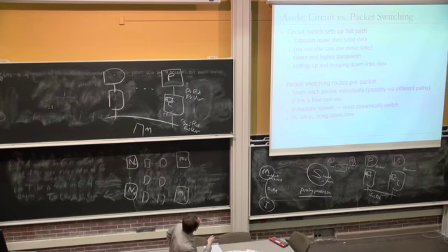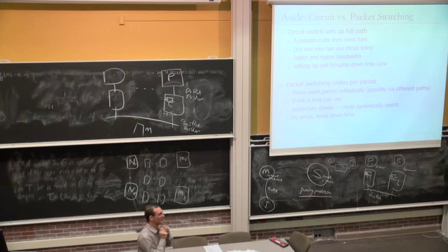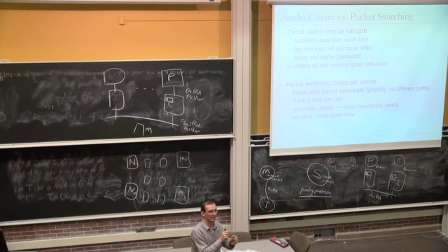Okay. Basically, you establish the route and then send data. No one else can use those links. That's the circuit switching method. It's faster and higher bandwidth, if you will, because once you establish the path, you can just stream the data, right? And you can optimize the router switch, because the switch doesn't need to arbitrate for each packet, right?